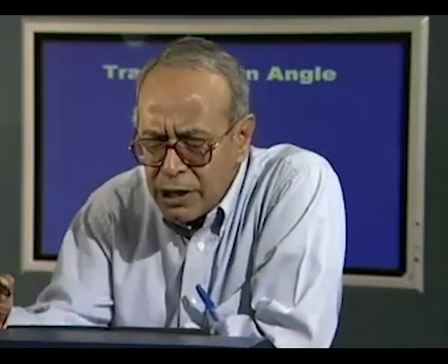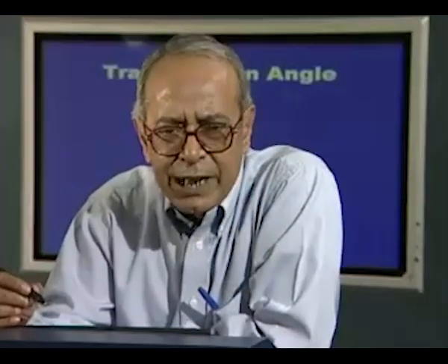Now that we have completed our discussion on displacement analysis both by graphical and analytical method, let me start with a very important index of a good mechanism. As we know, the mechanism has to satisfy the geometric requirements, but satisfying the geometric requirement is not all. For a real life mechanism, it must move freely, and this free running quality of a mechanism is quantified by a parameter which is called transmission angle. Let me now discuss this concept of transmission angle and show how to calculate the transmission angle at least for 4 link mechanisms.